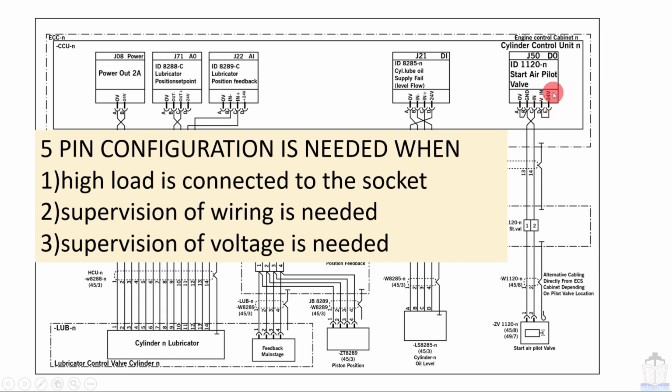That means here I am supervising this voltage. I want to make sure that before supplying this starter pilot valve, it should be 24 volt, or for example more than 20 volt. If it is less than 20 volt, I will stop supplying this starter pilot valve. This is called the supervision of voltage. This supervision of voltage is at many places in the MPC. You will come to know when we discuss the electric diagram, and I will tell you wherever it is. Okay, so this is all about the 5 pin configuration. I hope you have understood.